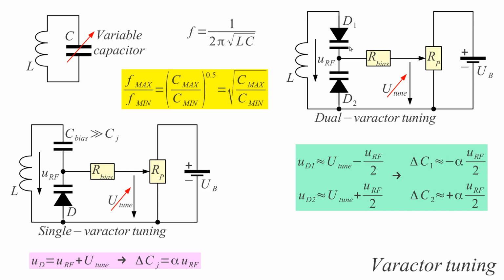Of course, the other thing to care about is to have a high impedance bias resistor here, not to load the RF circuit with this bias resistor, or an RF choke, but resistors are preferred to chokes, because chokes introduce additional unwanted resonances of our tuned circuit. So we have to be very careful what kind of bias device we put here.